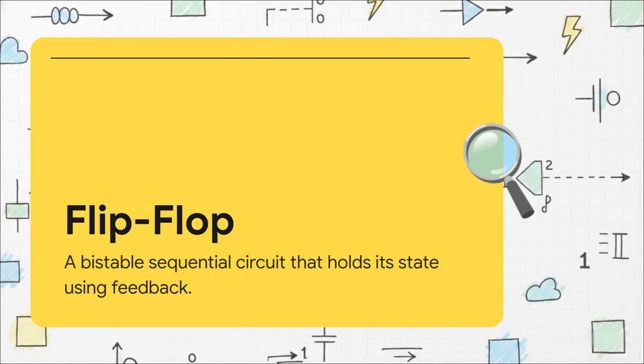Well, the brilliant engineering solution to that exact problem is the flip-flop. By definition, it's a bistable sequential circuit. And sure, it's built using standard logic gates, but it has this really clever twist, a feedback loop. This means the output's electrical voltage is quite literally routed right back to power its own input. This physical loop is basically a magic trick that keeps the circuit alive indefinitely, so it can hold on to its current state long after the original input signal vanishes.